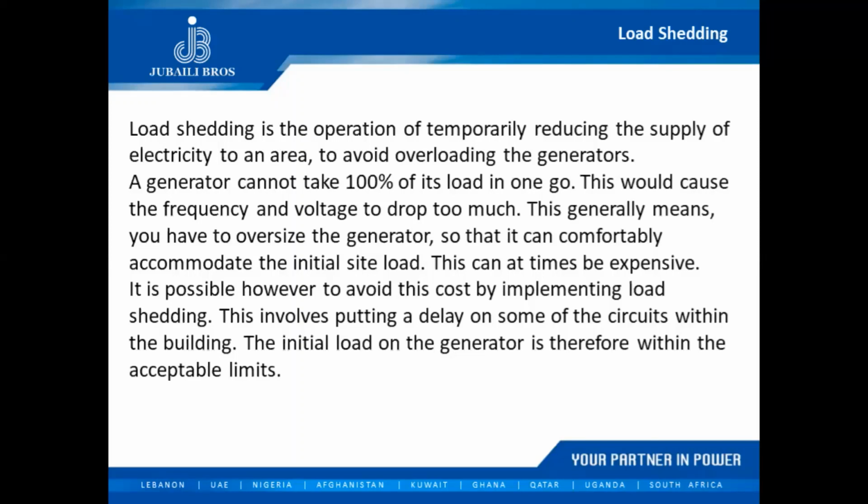It is possible, however, to avoid this cost by implementing load shedding. This involves putting a delay on some of the circuits within the building. The initial load on the generator is therefore within the acceptable limits. Too many words. In a nutshell, guys, load shedding is step loading. Okay, it's when I have a certain load and I divide this load into various steps rather than applying it all at the same time.